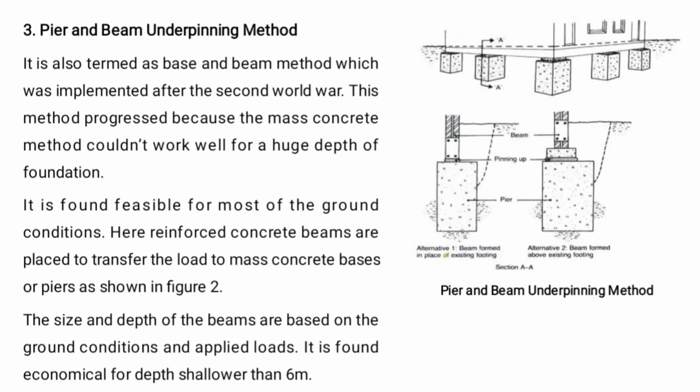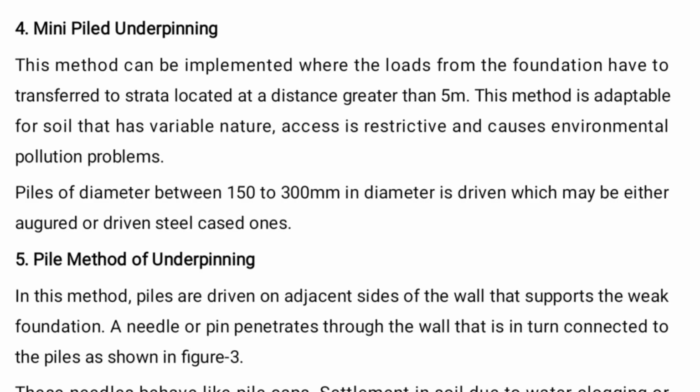Then the pier and beam underpinning method is feasible for most ground conditions. Here reinforced concrete beams are placed to transfer the load to mass concrete bases. The next one is the mini pile foundation, pile underpinning. Piles of diameter between 150 to 300 mm are driven, which may be either augured or driven steel cast.